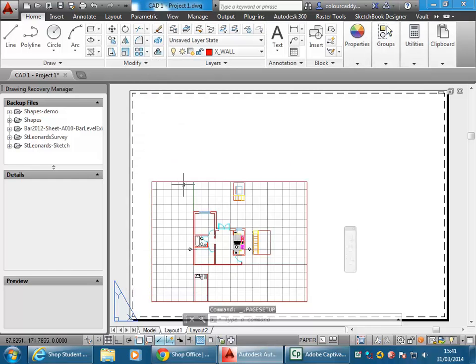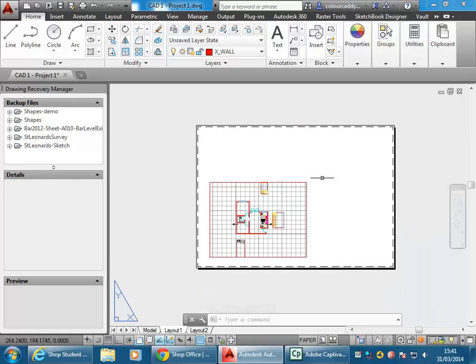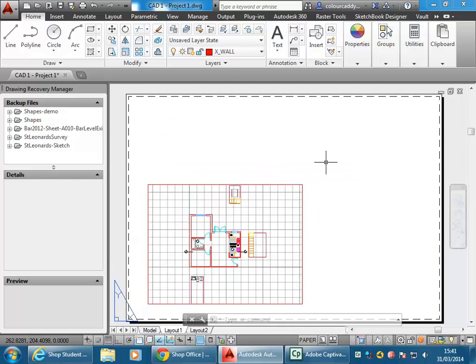And now you can hopefully see, before it was about the size of an A4 page, now it is exactly an A3 size page. It's good to get an idea of scale in reference to what we're working with now. So this is in AutoCAD space, the size of a real piece of paper. And then we've got this view where you can see the objects I've drawn inside this border. And that's a viewport. So if I click onto that border, I've selected the viewport.